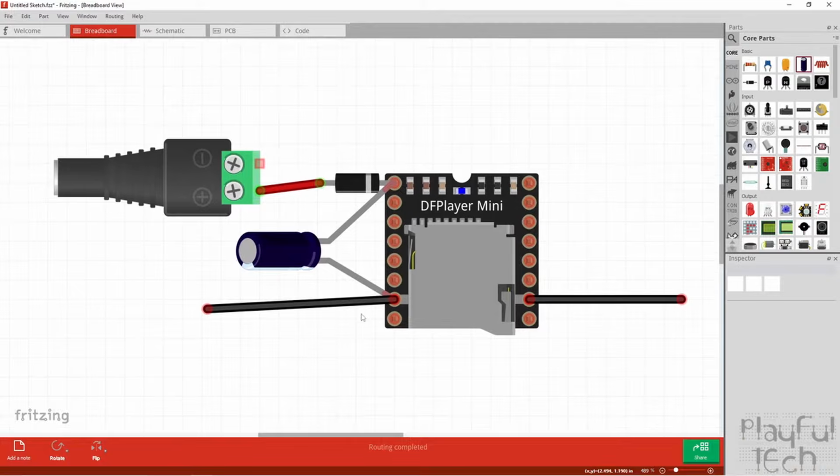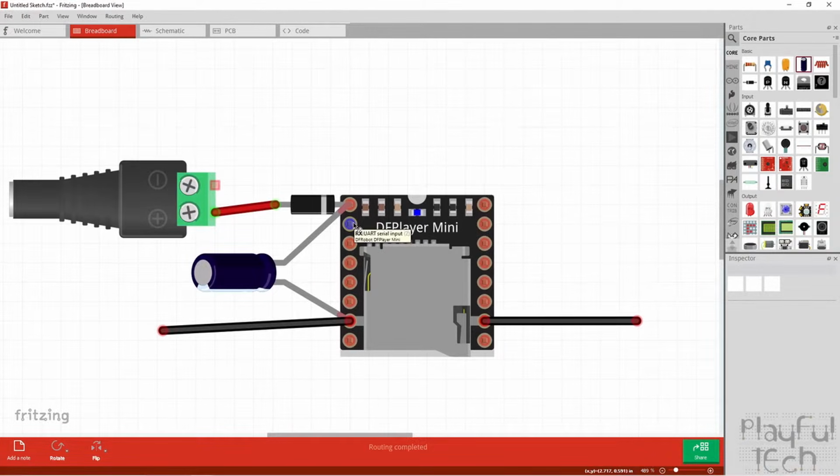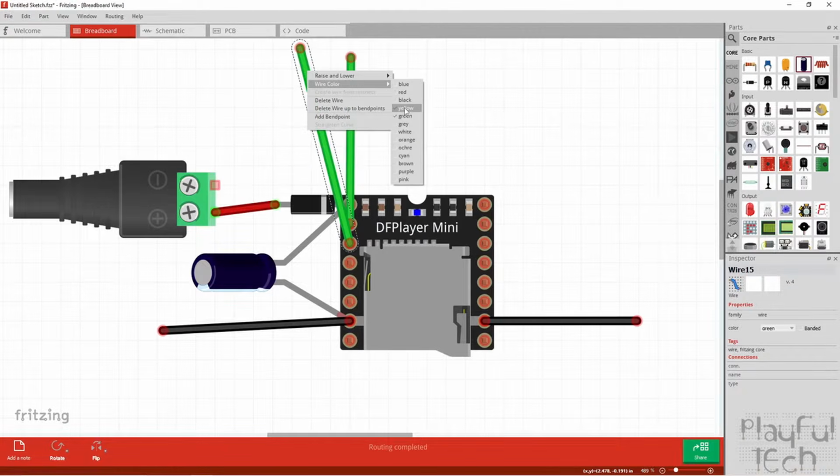And then, irrespective of the voltage that's being supplied on the VCC pin here, which we said is now about 4.2 volts, the logic level used on the interface pins is always 3.3 volts. So if you are connecting this to an Arduino, we've got the receive pin here, and we have the transmit pin, which sends messages back to the microprocessor here.